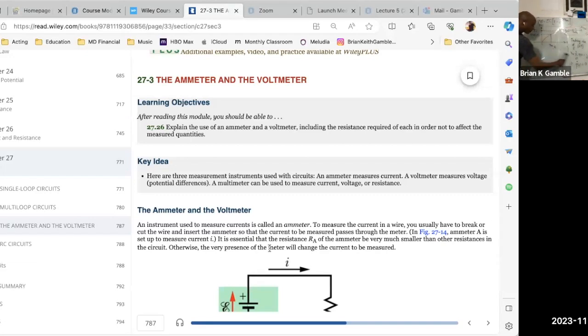And then you're back to doing separation of variables again. So you divide through by RC, and you get 1 over RC Q of t plus dQ dt equals 0. And then you can go through and separate variables again. I'll go ahead and finish.